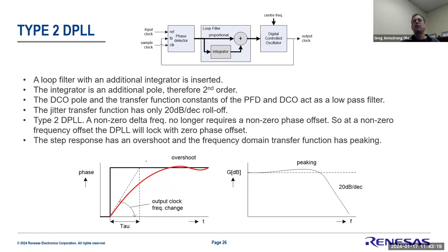So a lot of times the integrator is there to try to manage that gain peaking by keeping it very small, typically down to like 0.2 to 0.1 dB type of noise gain peaking that you want to see there. And so that's the advantage of the integrator, it allows you to not only control how quickly you respond, but over time it gets a nice average of your traceability to the clock, so that it represents the exact error of your local clock to the clock source that you're locking to, which becomes important when we start talking about holdover.